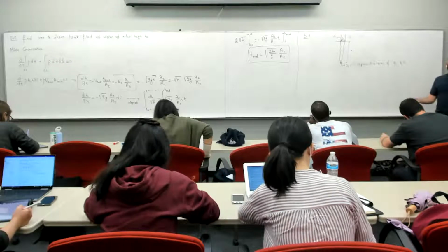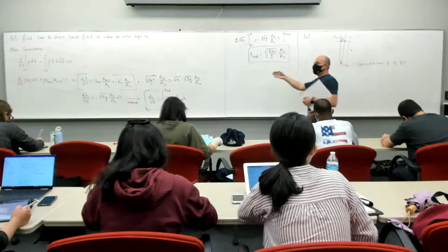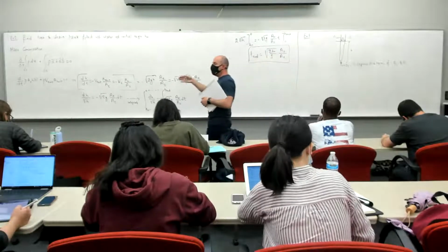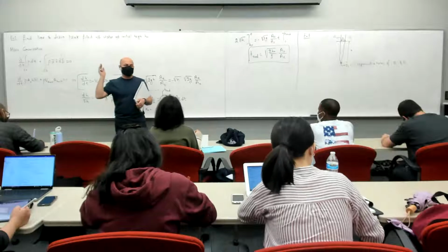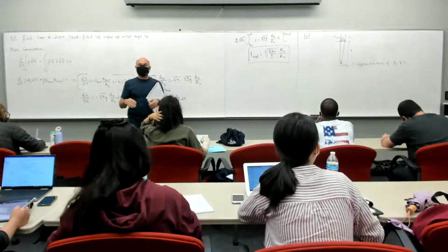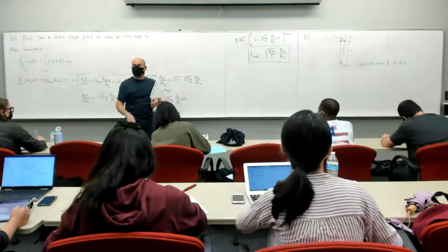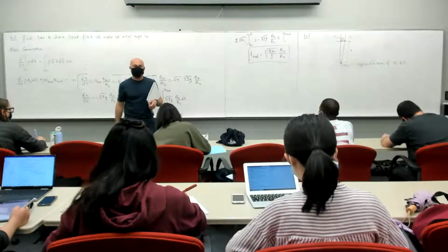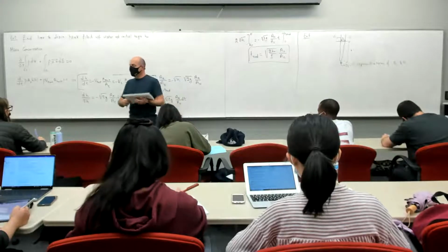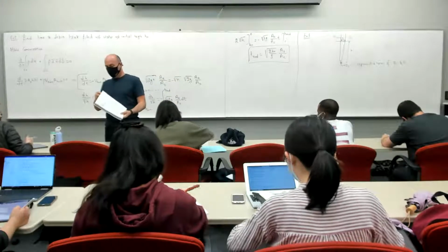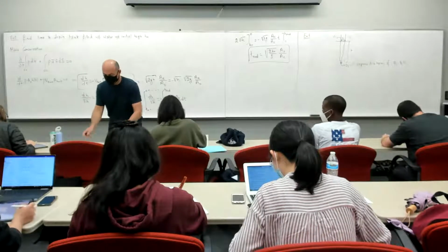You can work in groups. Okay. Again, see what mass conservation gives you, see what momentum gives you. This is a simple mass conservation problem, density is constant. So A1 V1 is A2 V2, right? So you can just write that down. Don't worry about proving it. And then let's see what you can do with it. Okay? Go ahead and work in groups.